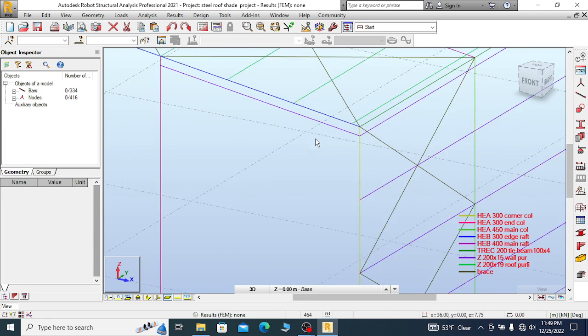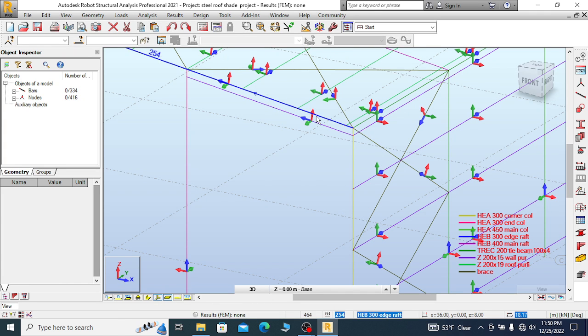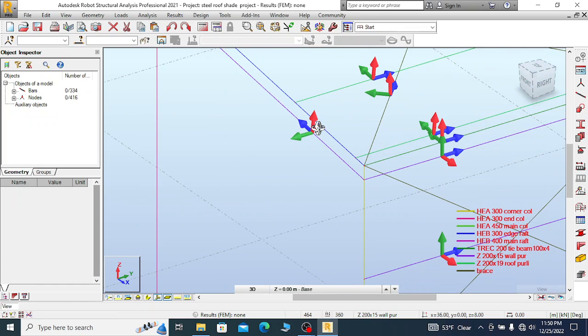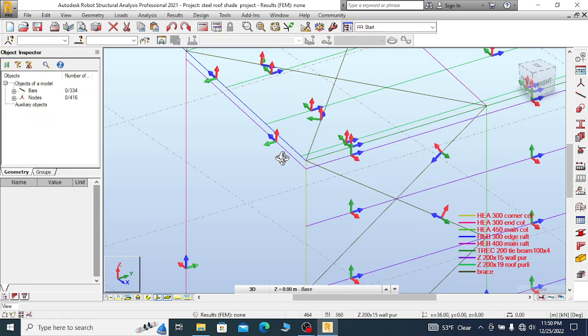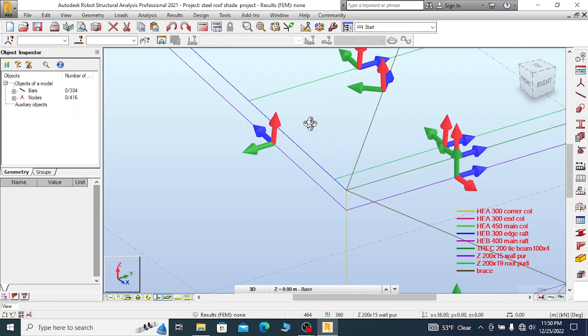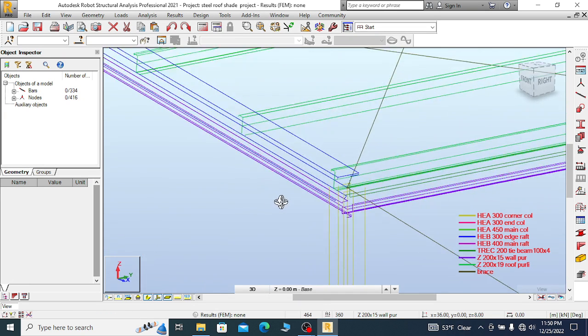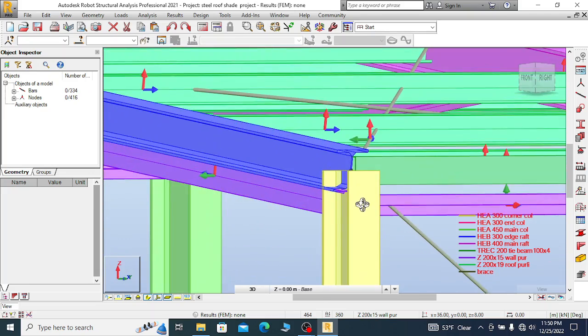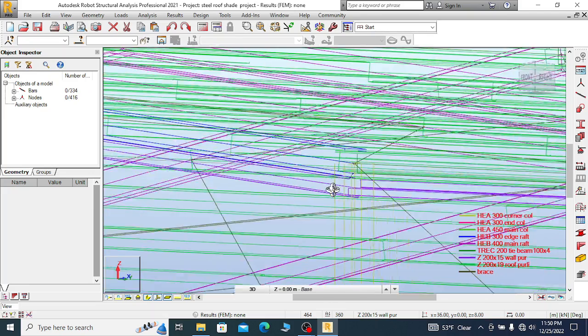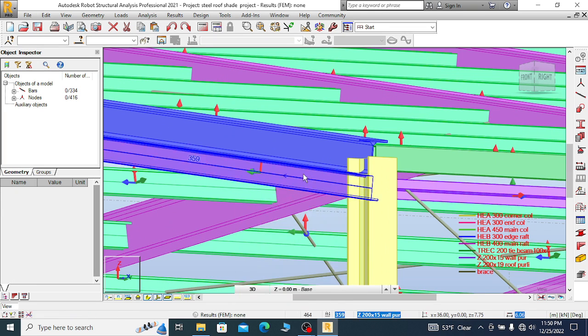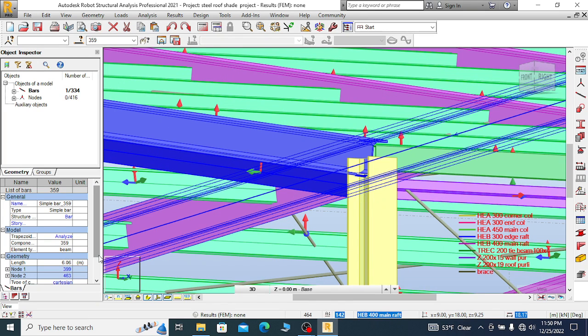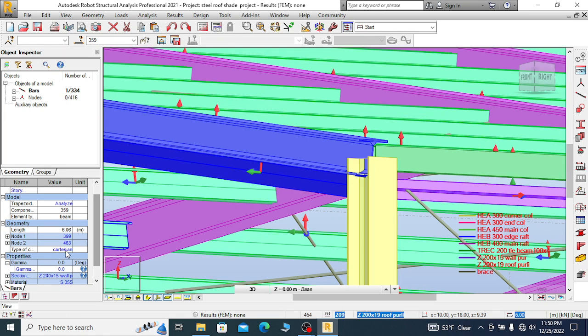So now let me see the local axis location. So this should be reversed. The positive Z axis should be located away from the shed of the blocks. So to do this, select this one and adjust the gamma angle.